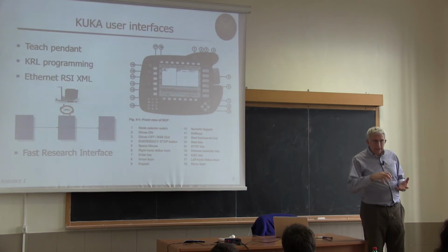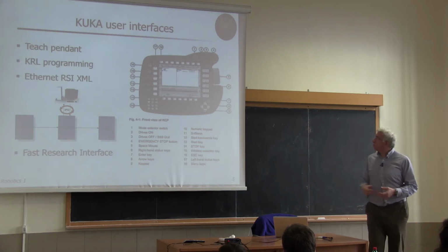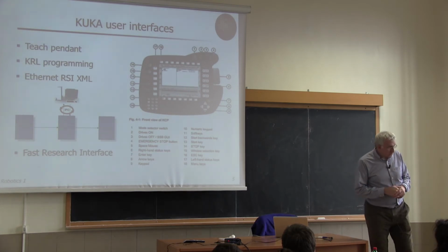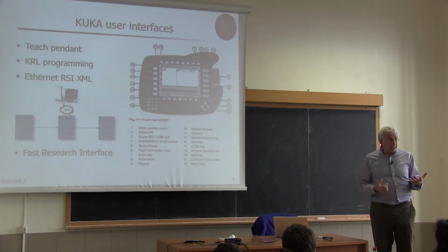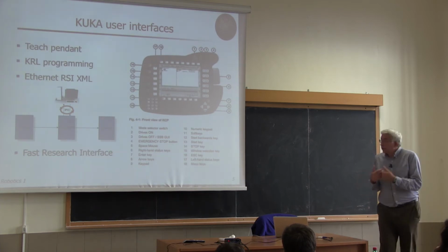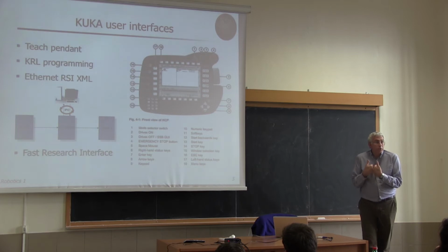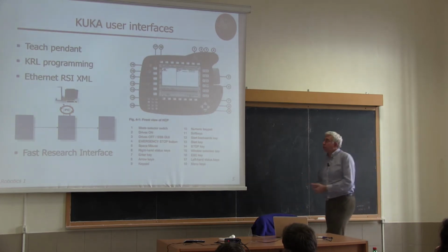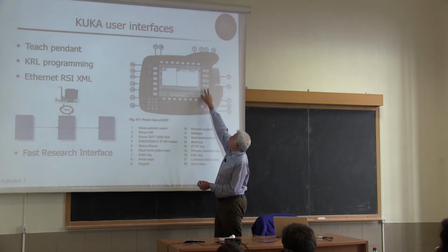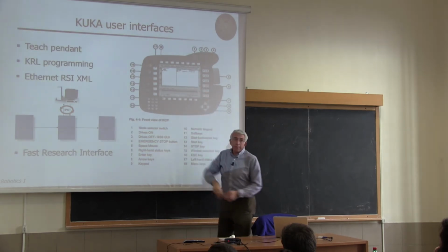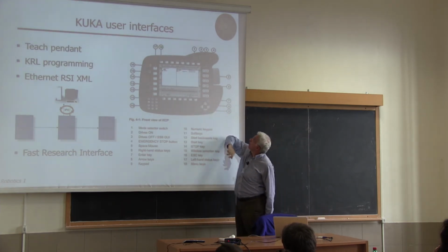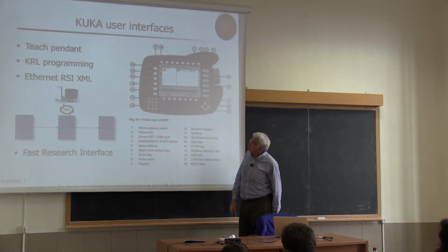Okay, so if you move properly this space mouse, you can move, for instance, 1 joint at a time, or 1 coordinate at a time in the Cartesian space. Okay, so at this level, it's the teach pendant. So the user is teaching the robot what to do. And then you can switch in speed or move joint by joint incrementally by minimum increments by this type of buttons, okay, 6 and so on.